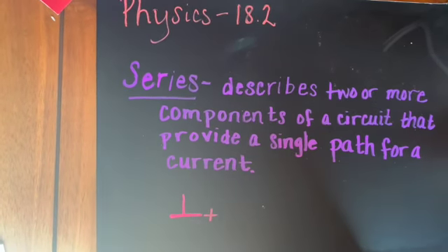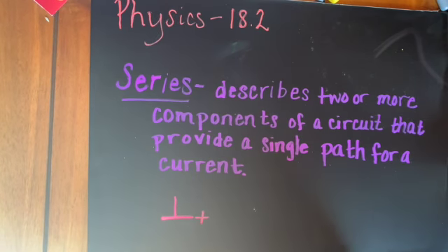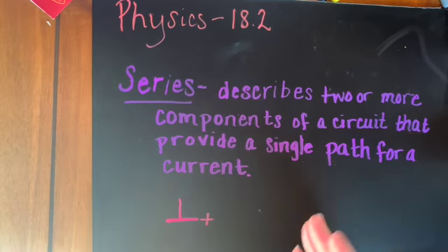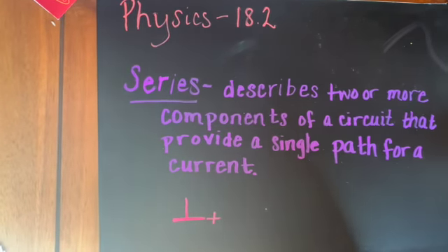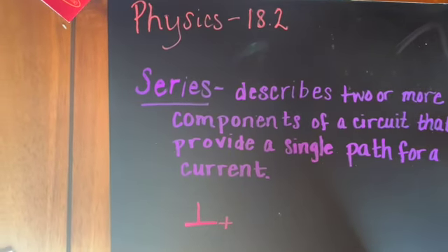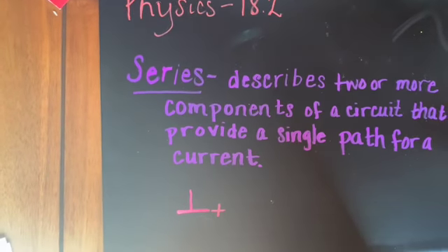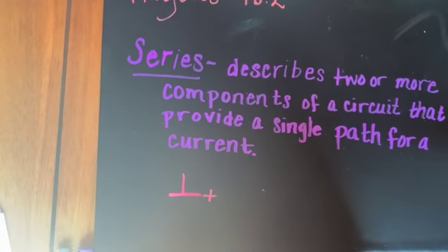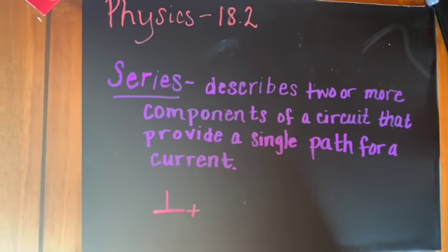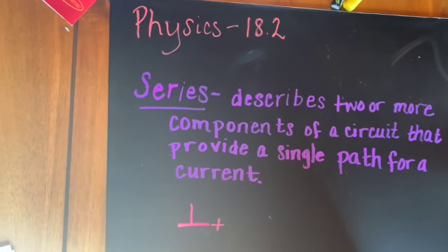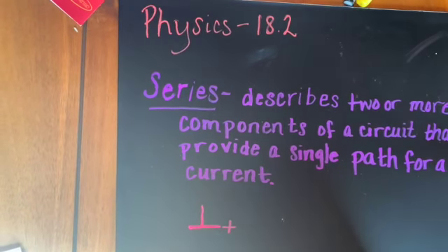If one light is out, the rest of the lights stay on. So in long strands of Christmas lights, if one of the lights is burnt out, you have a part of the strand that's out, and those are all the lights that are wired in series with that light bulb, and the other two parts are wired in parallel. So Christmas lights usually have three parallel circuits with bulbs that are connected in series.